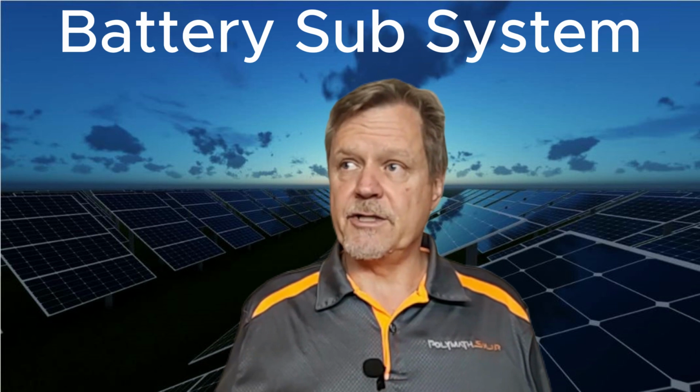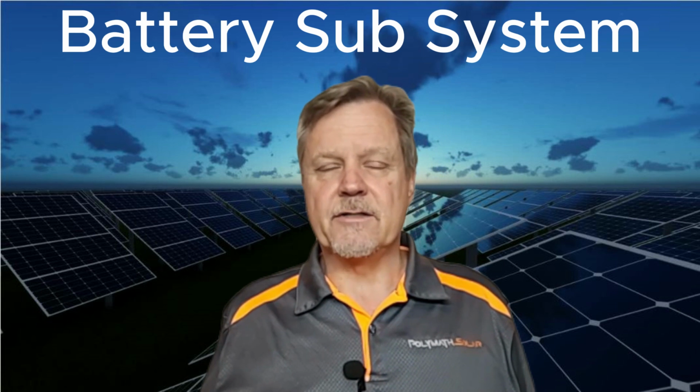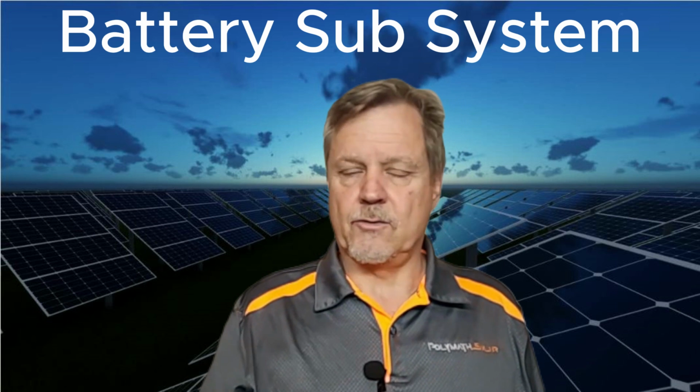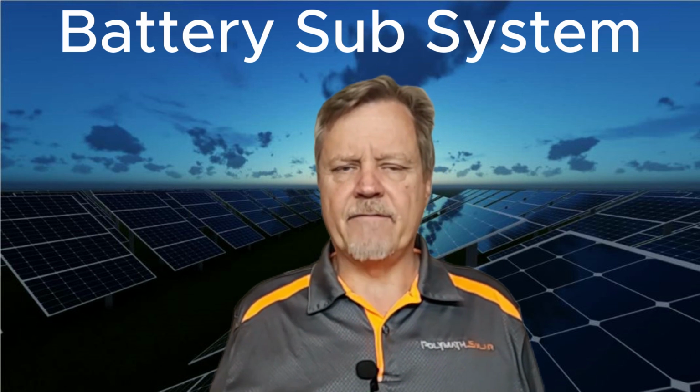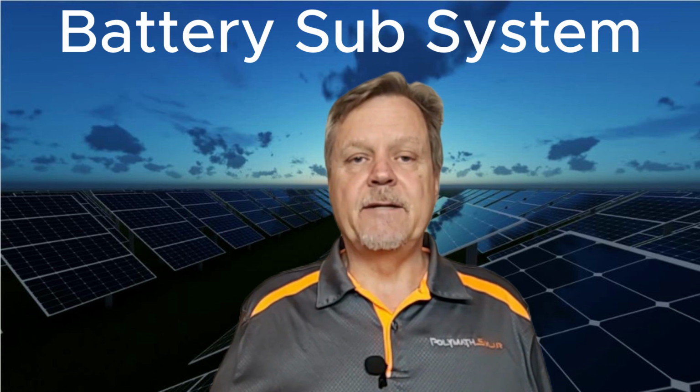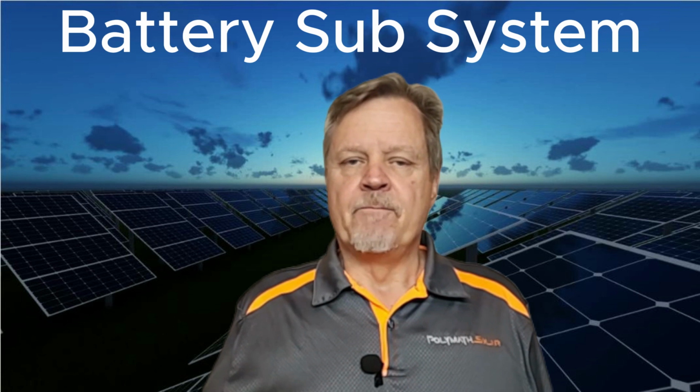So I often get the question, but how long will this battery last? Well, what is on at the same time? If you switch on your heater or your stove plate or the oven or whatever it is, that's a big drain, it's a heavy load. It will deplete the battery very quickly. But if you only have a few lights on, a light TV, a fridge, then a smallish battery can take you easily through 4 or 5 or even more hours, depending on what's on it. So the bigger the load, the quicker you are depleting the battery. Make sense?